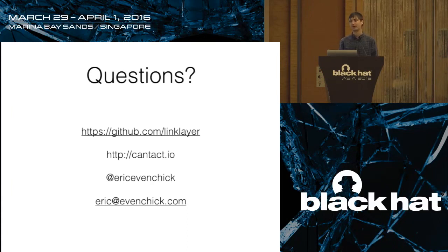The really naive way of doing that is because we have these signal databases that define everything that should be sent, the valid ranges for all of those signals, the rates at which they should be sent. You can do some basic heuristics to say, oh, well, this message is being sent too fast or with out of range values, and use that to determine that some breach is happening.